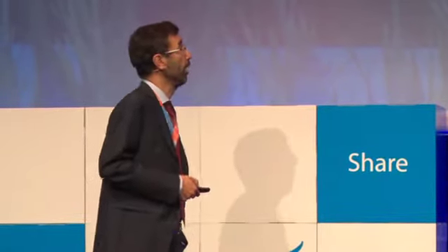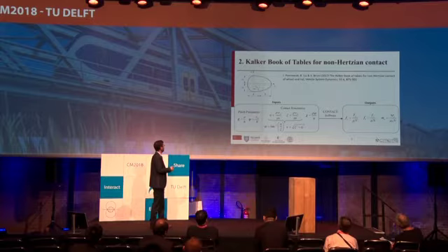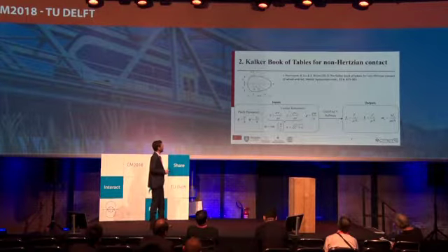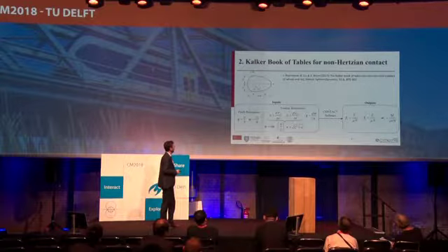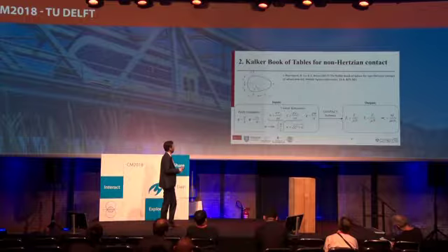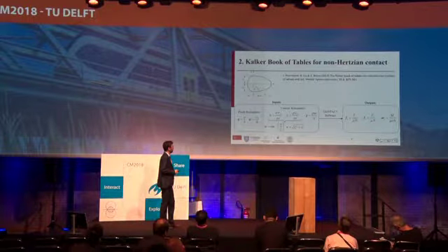And then if you want to build a contact table out of this, besides these two geometry parameters, you have some parameters for the creepages and spin creepage, and there we use non-dimensionalized longitudinal and lateral creepages and non-dimensional spin creepage, which we then turn into a magnitude of the non-dimensional creepage and an angle for the non-dimensional creepage.